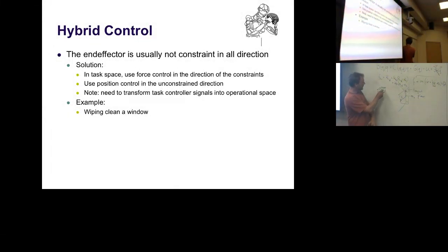So what you do essentially, you want to touch here, you take a bunch of neighboring points, and what you fit is a linear tangent plane to the data points. It's just a simple 3D linear regression problem. I'll tell you a little bit about linear regression when it comes to adaptive control, but it's super trivial to do. From that, you get at least a noisy estimate of the tangent. Sorry, the normal, or the tangent, whatever you want. You can get both. So the plane is the tangent plane, and what's perpendicular to it is the normal.